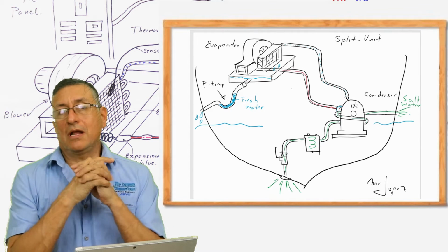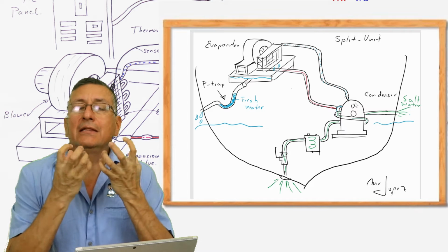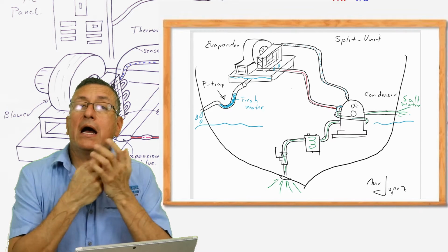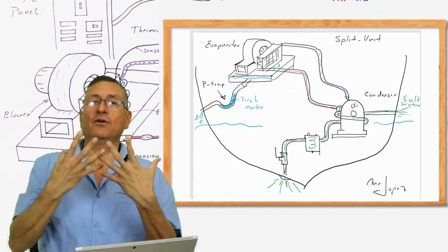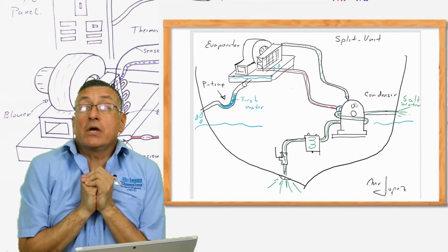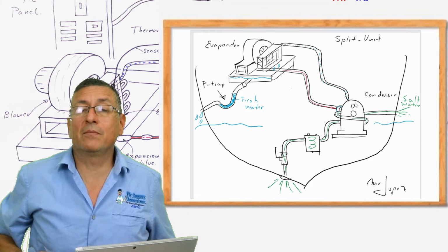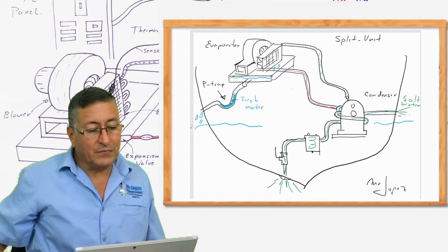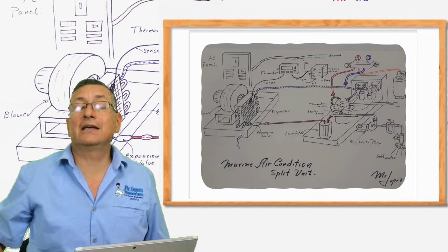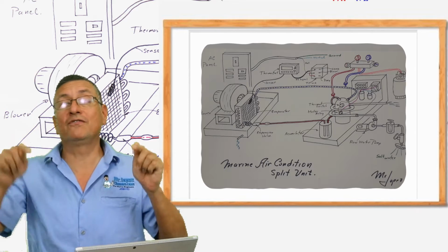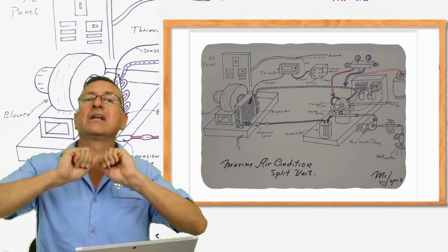Right now, we are going to talk about the evaporator, and we are going to try to understand what happens internally in the evaporator and why on one side air enters at ambient temperature, and on the other side you receive cold air. This is basically because of the refrigerant. You remember the refrigerant in the cycle. This is the magic part of this business. In one portion of the cycle the refrigerant absorbs heat, and in another portion of the cycle it releases heat.